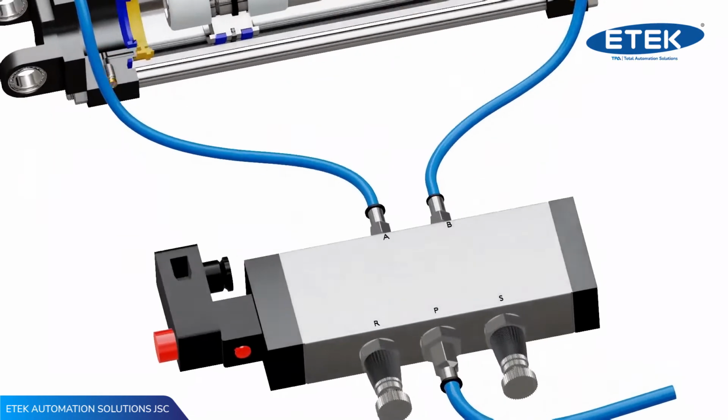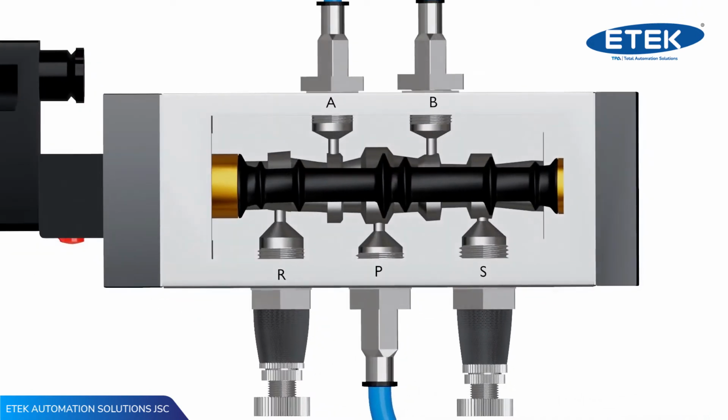The valve shown here is a 5-port 4-way valve. Ports A and B are connected to the cylinder. Port P is connected to the compressed air supply unit. Ports R and S are exhaust ports to which the pneumatic mufflers are attached.